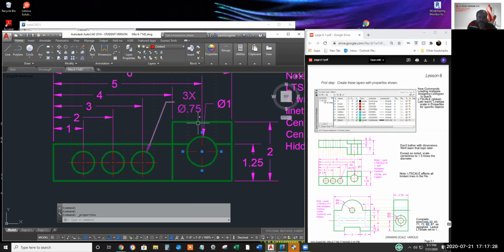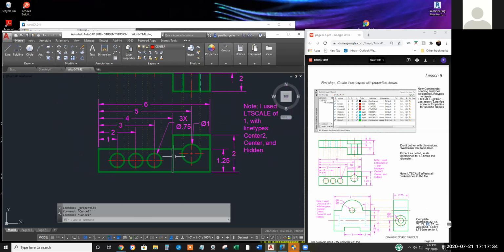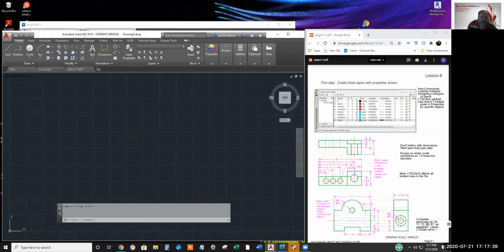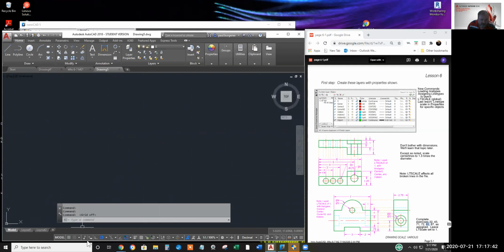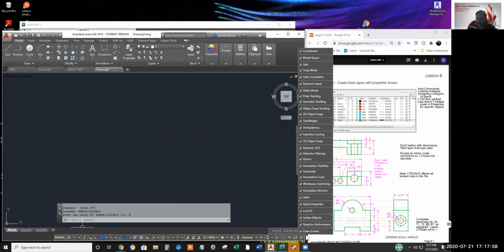Now remember, let's try to be consistent. Let's start a brand new drawing. Close, shut off the annoying status bar, double check, should not change, but double check my polar tracking and those snap settings. Just for good measure, I'll double check I got all status bar buttons visible. So nothing could be invisible but on.